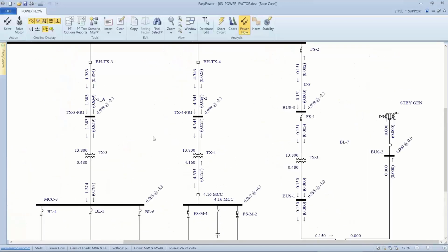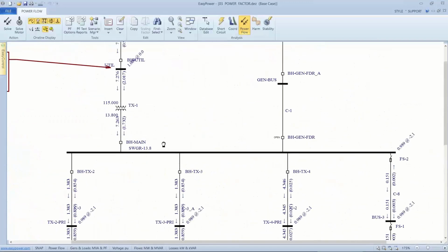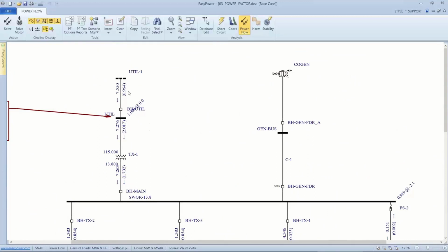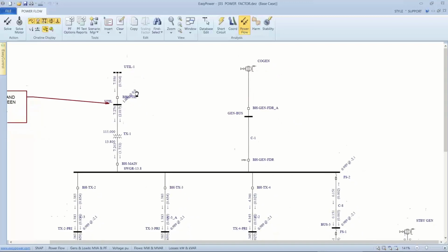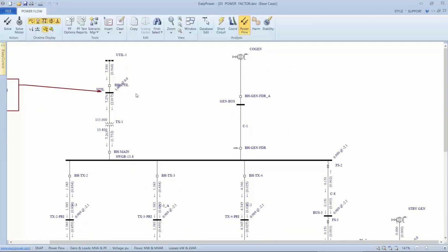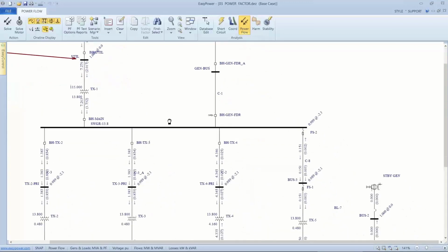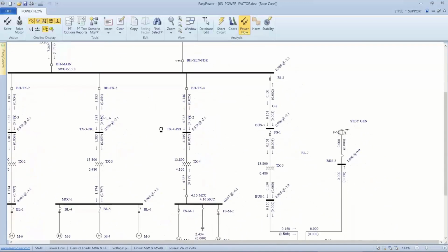Now, what did I do to our power flow with the utility? It brought the power factor up to 0.96 and eliminates the power factor demand penalty to the rate of $10,000 a month in some cases if we have this on full time.